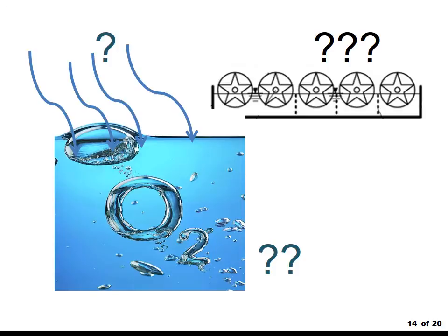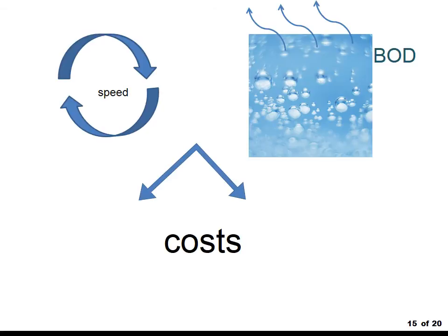This data can be changed in the calculation, and by changing also the rotational speed, we can find the best possible way for removal of BOD, or biological oxygen demand, and after that we of course need to think about cost. What are fixed costs, what are costs we can have an impact on, and how to make the system work.